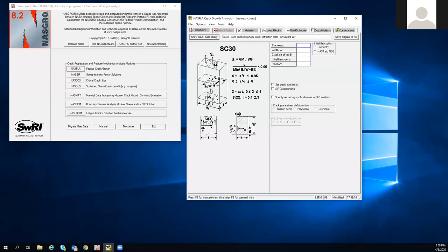magnetic particle inspection. All of these different inspections allow for us to either do surface detection, like visual or dye penetrant, where you just smear a dye over a surface and then you use like a black light in order to make that dye kind of pop out at you. Or if you're using things like X-ray or ultrasonic inspection that can go through a solid, those are called volumetric inspections, that can detect things like embedded flaws, things that exist inside that wouldn't exist on the surface.